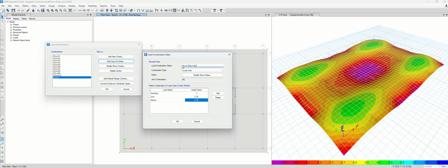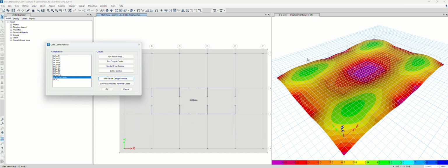But here you see that dead load and live load are unfactored, but wind X, when we bring it from ETABS, is the ultimate wind load. So we need to convert the ultimate wind load to service wind load, which is 0.6. We take 0.6 on our factored wind load and multiply by 0.75. So this is a load case where the wind is blowing in the X direction. Let's take a look at the soil bearing stress diagram. Let me create another in the Y direction.